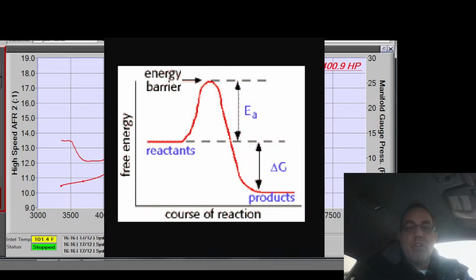But then as the pressure goes up in this cylinder, it heats up a little more, it just tips the scale, boom, and the reaction starts to happen. And so that little spot on the head that had high energy, had extra heat, and then the combination of that and the pressure, boom, puts us over the edge, and we start a reaction, and our combustion starts to happen. Well, this same thing happens with the spark plug. We have all this stuff in there. We're squeezing it, and then we add a spark, and that knocks us over the edge, and then boom, we initiate a reaction, okay?